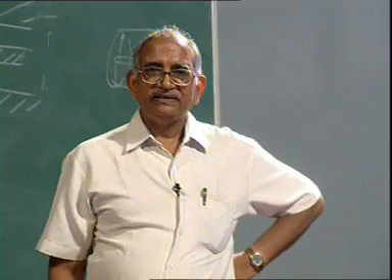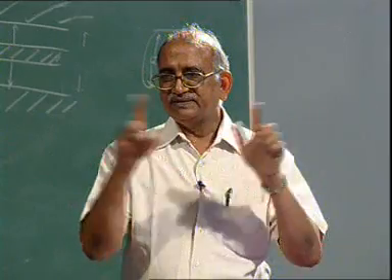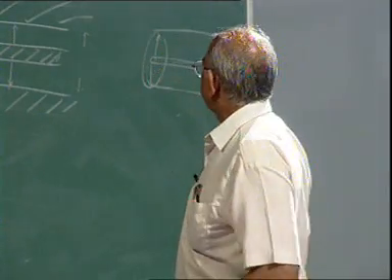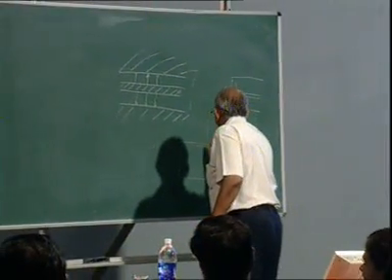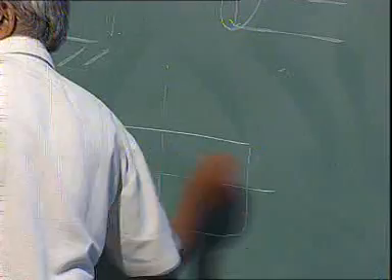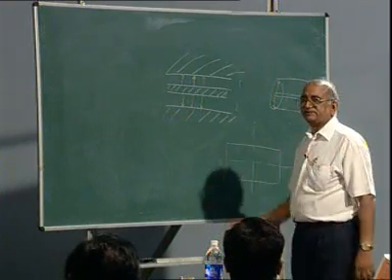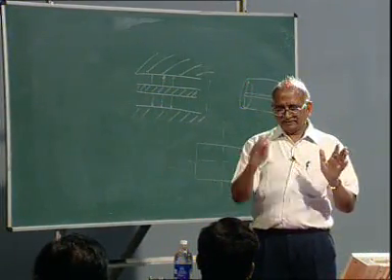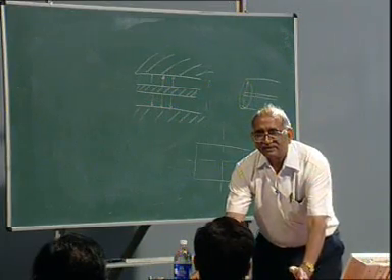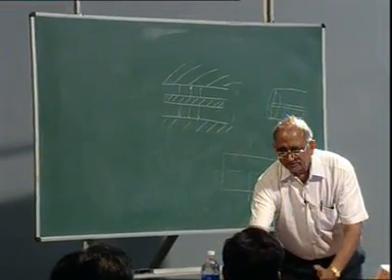Because when you are measuring the radiation pattern, normally you measure it in 2 orthogonal planes. That is, if this is your patch antenna, you will measure the radiation pattern in this plane and this plane, going from one end to the other, along the half sphere. Along the half sphere, you move your receive antenna. In one case the receive antenna will move like this, in the orthogonal plane it will move like this.